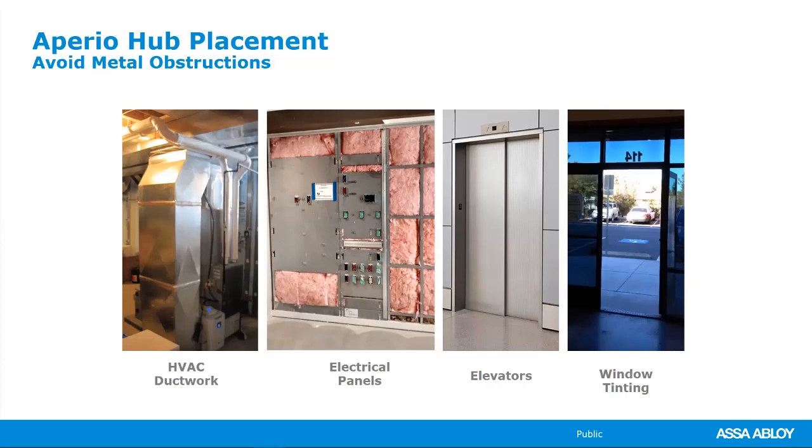Elevators, when you're doing your survey, make sure to conduct that survey with your elevator on the floor you're on and above and below. Depending on the elevator, there might be some kind of sensor on that, and so you want to make sure you cover all your bases. Nothing would be worse than testing it with the elevator 3 floors away, but when it's on your floor, it's giving you some signal interference.